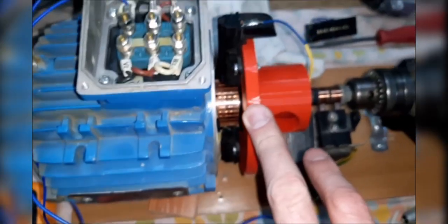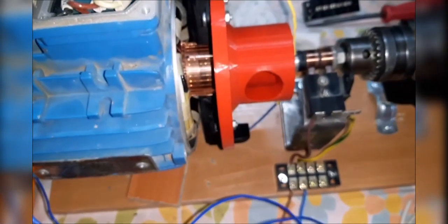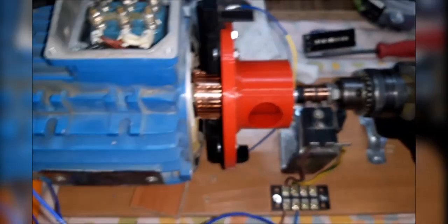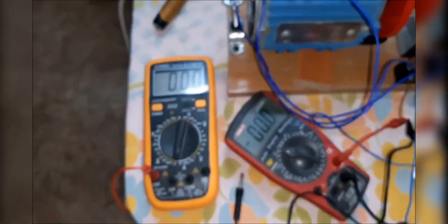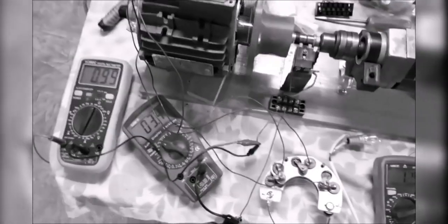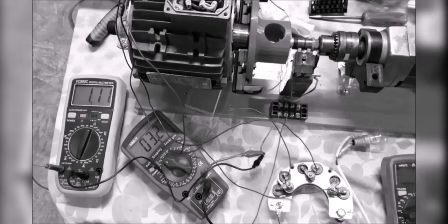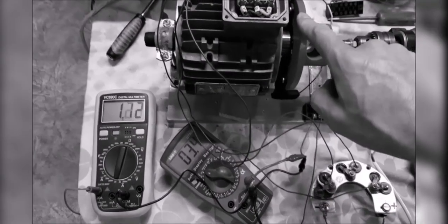2. Find a stator with slots so that your anchor fits tightly into the stator without a gap, or with a minimum gap. Provide a uniform gap between the stator and anchor bars. 3. Wind the stator winding for a three-phase generator system with two-pole rotor excitation. I think a simple winding mechanism is available online. If you already have a ready-made winding from a three-phase motor for test runs, use it, but for a generator this is not the best option. Connect the stator winding through a three-phase diode bridge to an adjustable laboratory load for measurements.